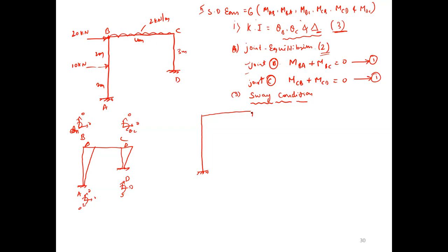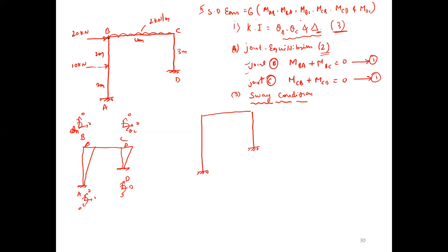I am considering only the frame and joint load. See, in this problem, I have mentioned a joint load. In FEM, you are not considering this joint load. Where do you have to consider this joint load? In sway condition, you must consider the joint loads.